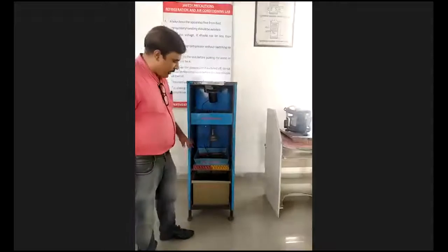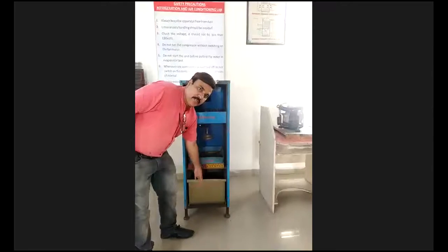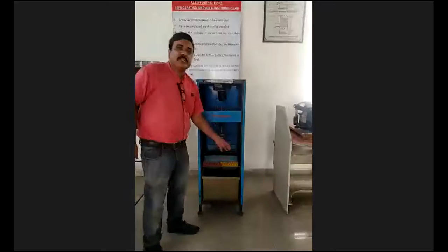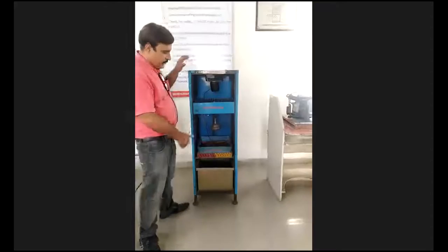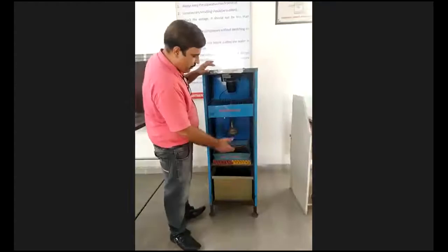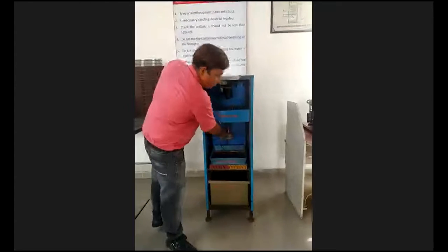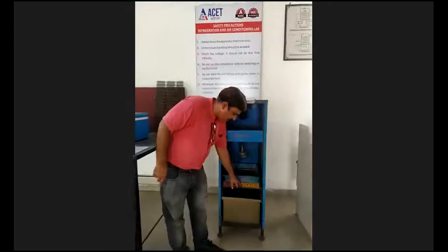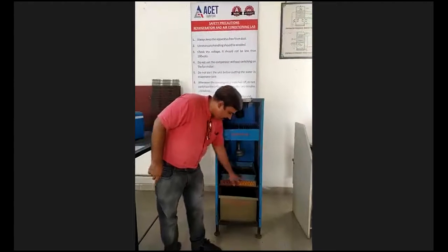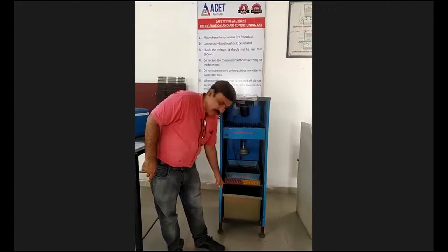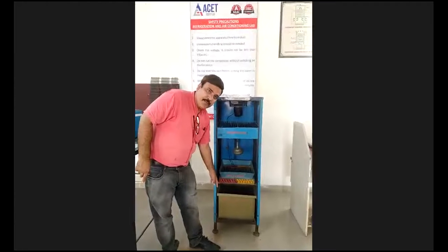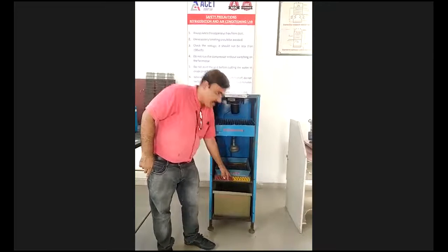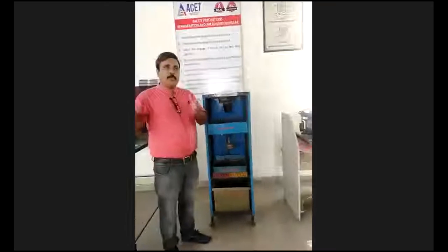And this is the water tank. Look here at the bottom side of this evaporative type condenser. This is the water tank, in which a water pump is also placed, through which it circulates the water through this nozzle. So when all the vapor refrigerant is going through this condenser, look here, this is the condenser. From the compressor, high pressure, high temperature vapor is coming through this pipe. Look at the red area, through which hot vapor is coming from the compressor.